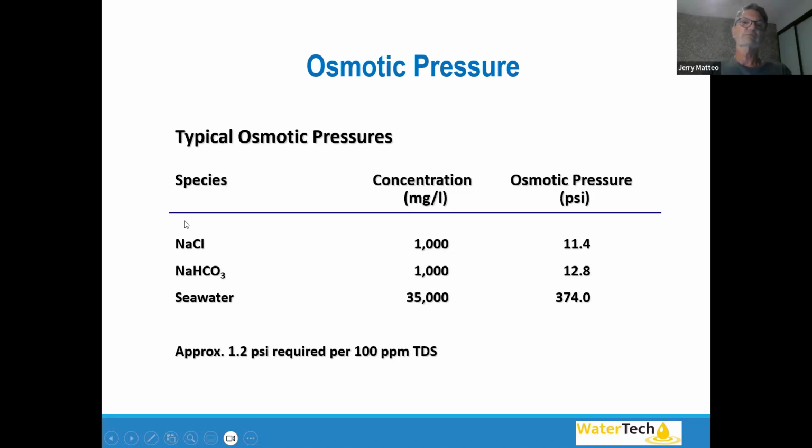If we've got fresh water with, say, 1,000 parts per million of dissolved solids, we've got less osmosis. So if we don't have that much pressure in these cases, for seawater here, for fresh water there, we won't start to drive the fresh water through the membrane. We don't have enough pressure to overcome the osmotic pressure that's created by the amount of dissolved solids.